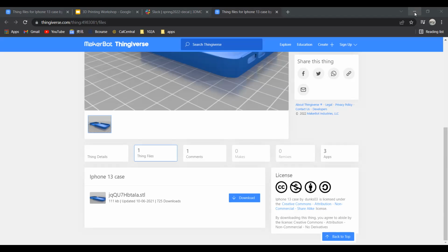All right, so now let's insert the file. When you want to insert an STL file, you want to use this Insert Mesh button under Insert. Then find your file, open, and change this to millimeter. It's like the standard industrial unit.